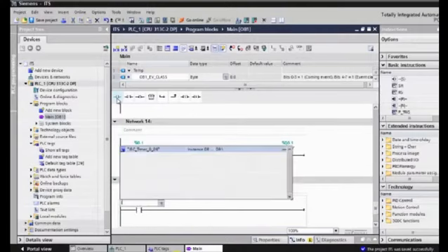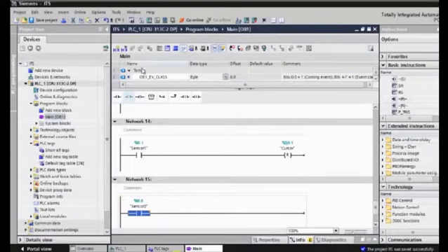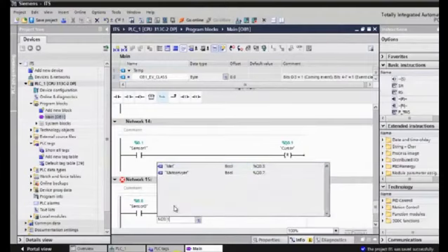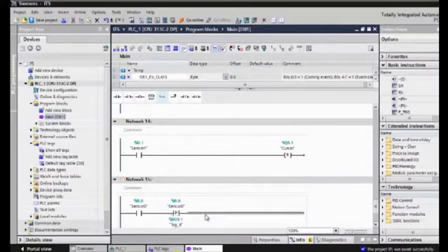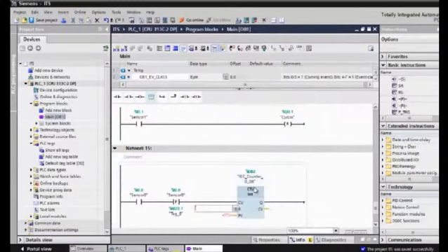It will be counted by sensor 0 by the positive edge, just like before, and this for a marker. Let's call this marker M20.1. We are going to use counter up. This counter should count 2.